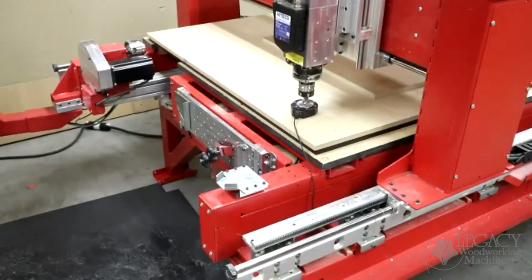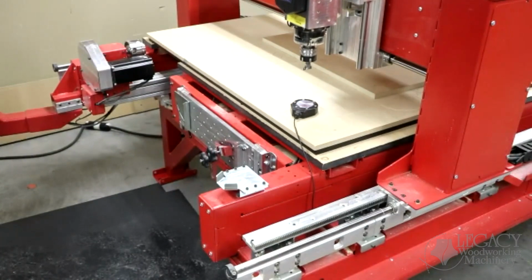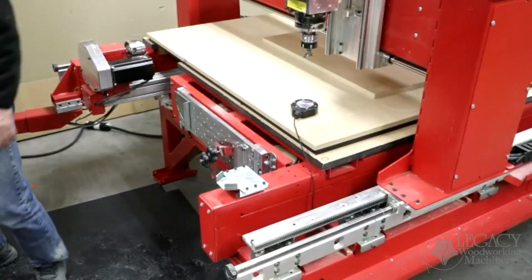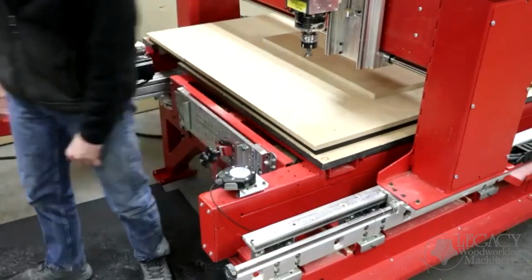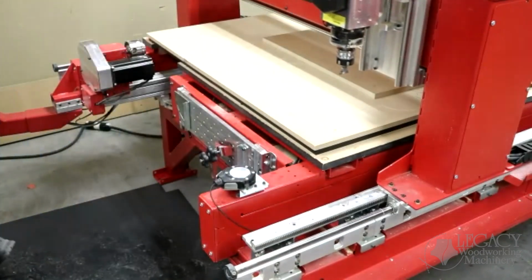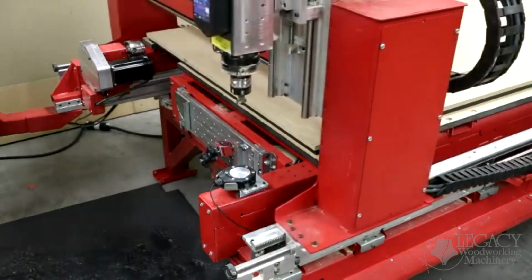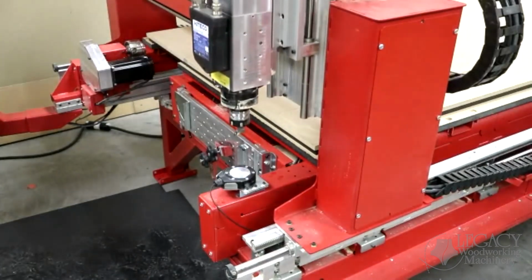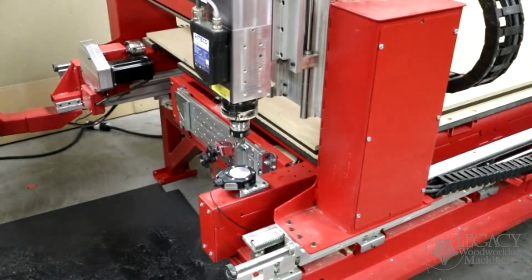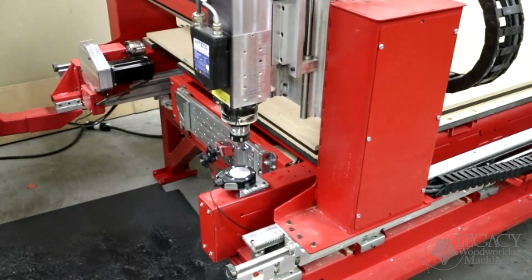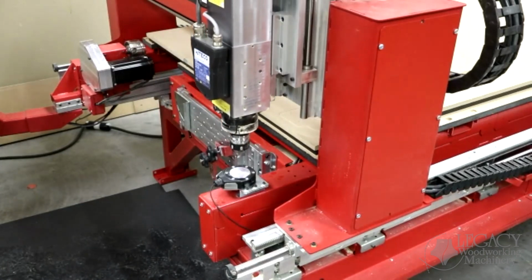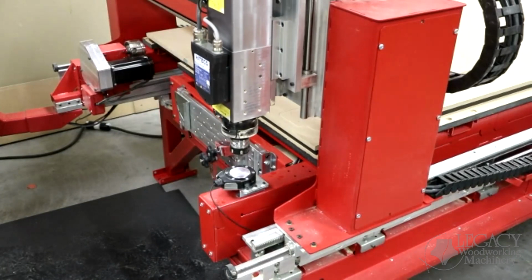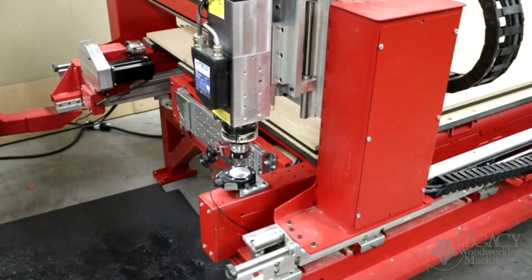You'll notice that it touches twice right there. That's the first time to find it, the second time to give it a real accurate reading. And then it waits for you to move it over to the home position for the Smart Tool. What you just saw right there, that rapid movement, is called the rapid Z. We'll get into that more in a minute, but it saves you a lot of time, because if you don't have that on, it'll probe the entire distance, which would take you a very long time.